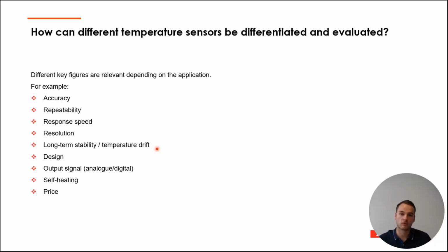For example, with our sensor, you have a temperature drift usually less than 0.01 degrees Celsius a year, while for other technologies, the temperature drift could be 0.5 degrees Celsius, which is a factor of 50 difference. That's a lot, and possibly could save you a recalibration, which is really expensive.